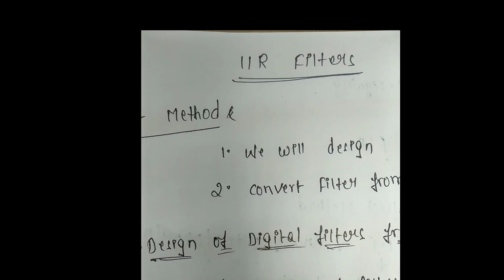If you want to understand it in a better way, infinite impulse response means you give the impulse as an input and it produces its response continuously, infinitely. Such systems are called infinite impulse response. How is it possible? This is possible because of the feedback provided.